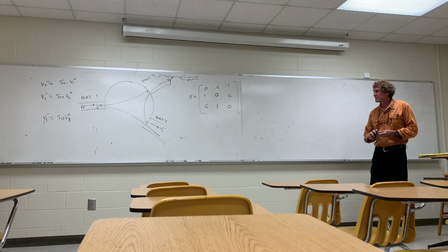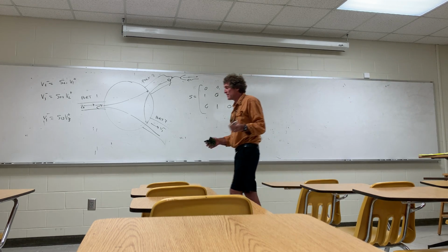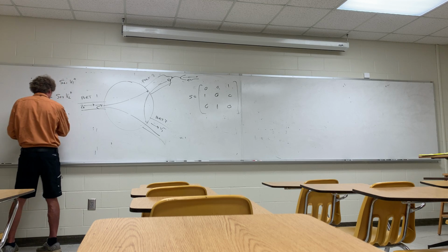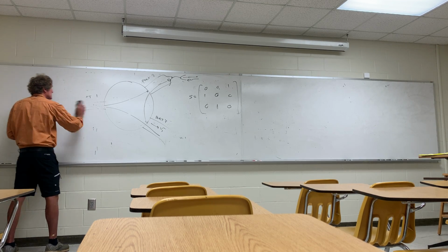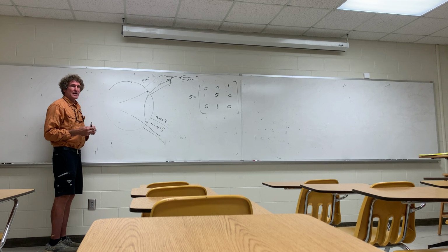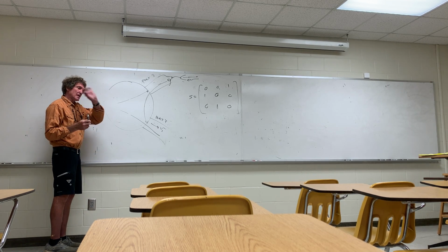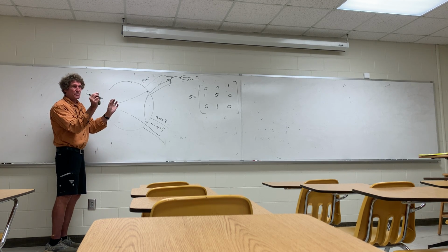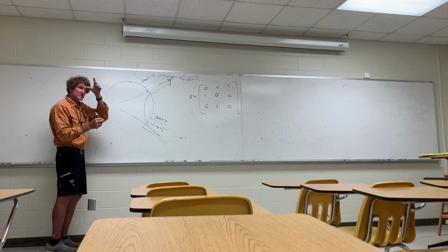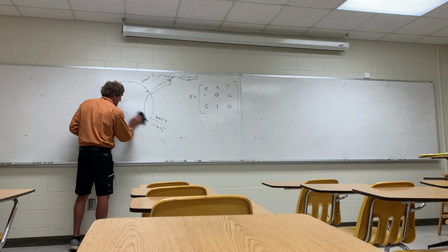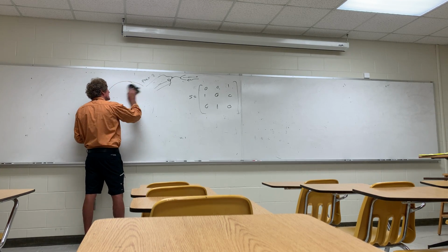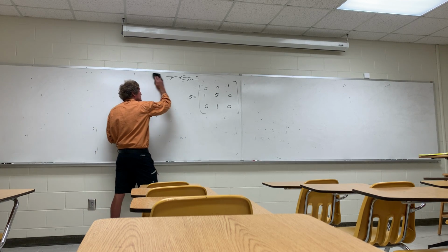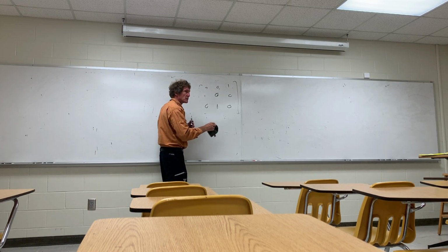Next, 3-port dividers. This is something a fair number of you probably have experience with. I think you call them splitters when you're dealing with cable. Has anybody ever got a splitter? In other words, you take a cable signal in, and instead of having one connection out, you have two. It's called a splitter. Anytime you split a signal, you reduce the amount of power available at each port. And depending on the type of splitter, you're going to lose a certain amount of power. So what we're talking about is splitters, and this is used all the time. You probably used them when you connected the cable network inside your house, and you wanted to run cable in 2 or 3 different rooms.